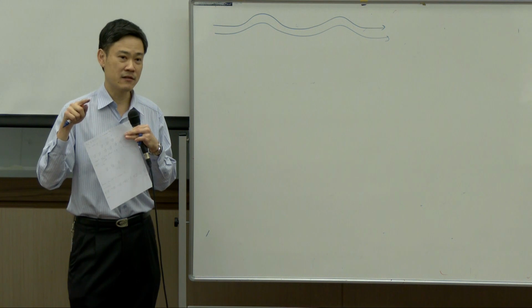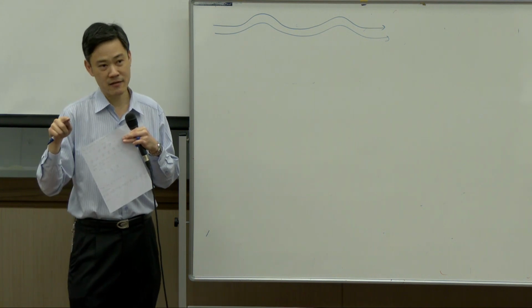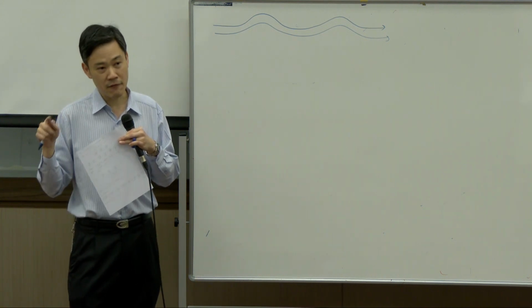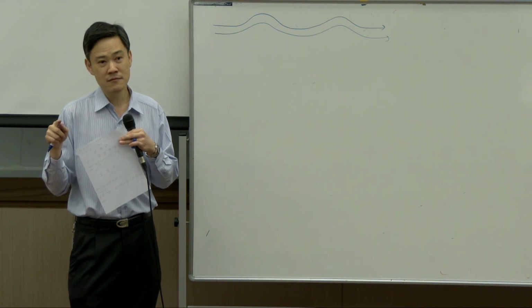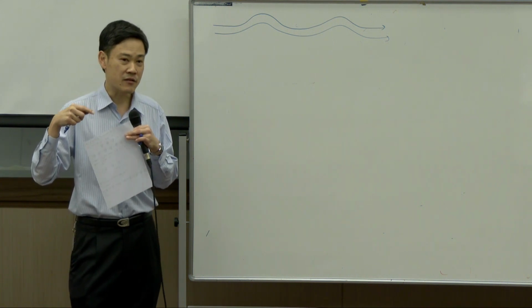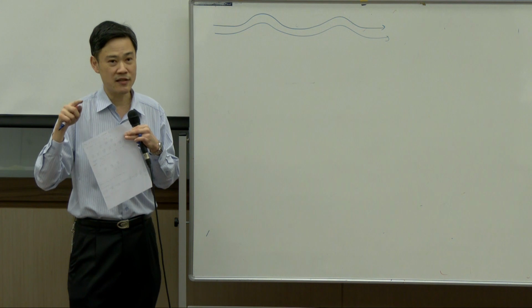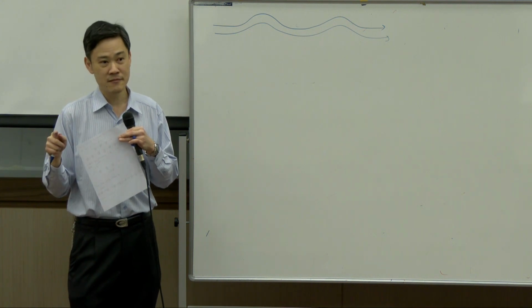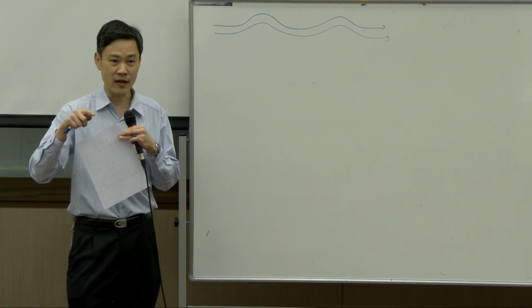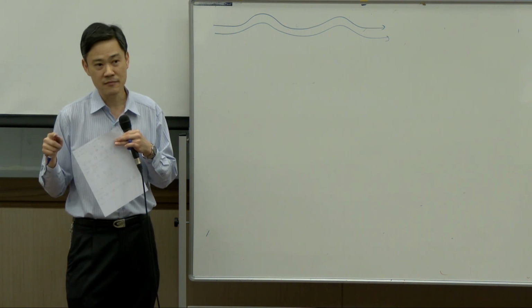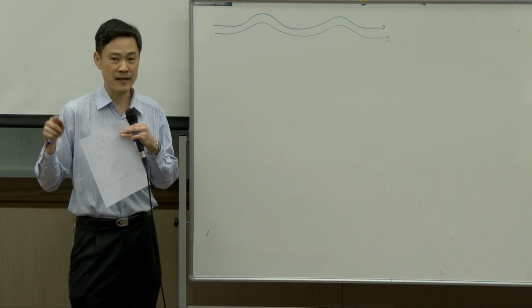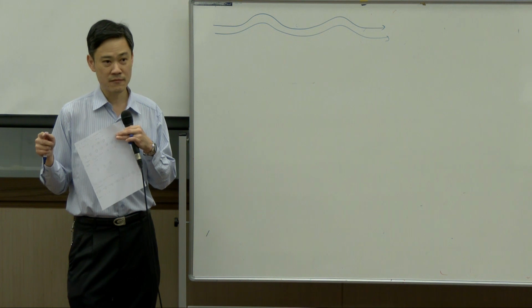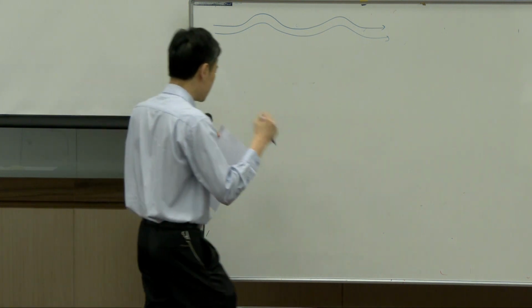But wait a minute, what about steady state? Can we have steady state turbulent flow? In our mind, the term steady state means it is not a function of time. But as I said earlier, turbulent means it changes with respect to time. Can we have turbulent flow at steady state? The answer is yes, you can.